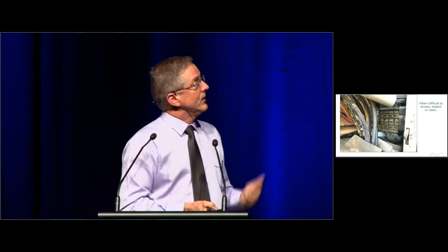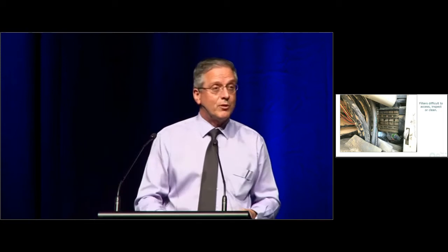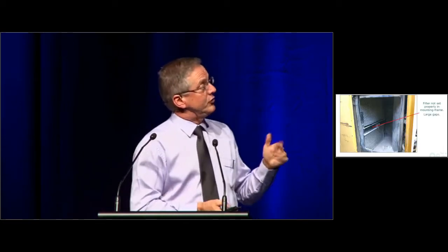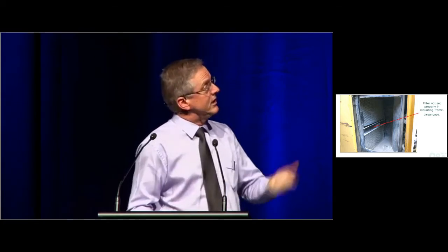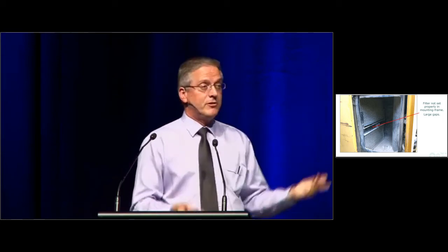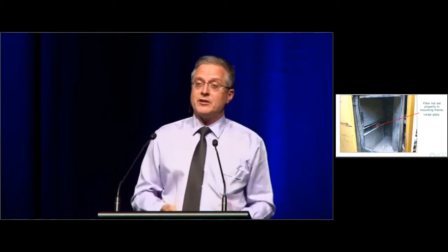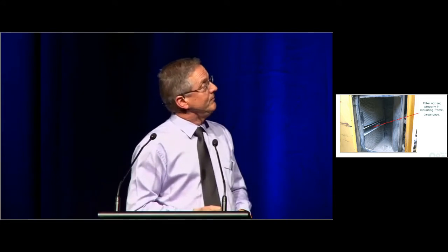Overloading, again, difficult to access and maintain, and this one clearly hadn't been maintained for a while. This one's a filter in a mounting and just wasn't mounted correctly when it had been put back in. It's not sitting in the mounting frame, the bracket's in the wrong place. So you get a big gap there, and air's like water, it'll follow the path of least resistance, so your dusty air is going to track through that hole rather than try and work its way through that filter.